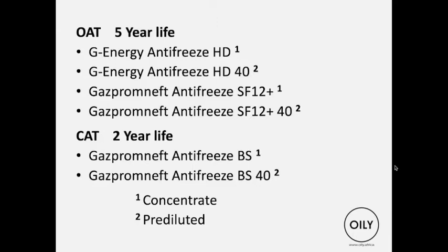Because HD, it's approved by Cummins and Caterpillar and Detroit, Freightliner, etc. Freightliner, for instance, makes trucks. They do not make engines. You can specify a Caterpillar, Cummins, or Detroit diesel engine in a Freightliner. Caterpillar, Cummins, and Detroit diesel engines all have their own antifreezes, and they're incompatible with each other.